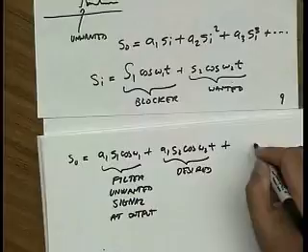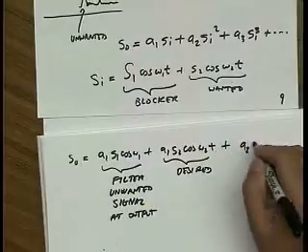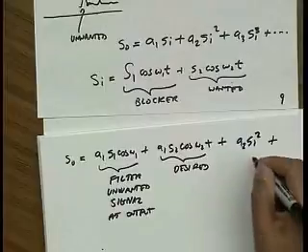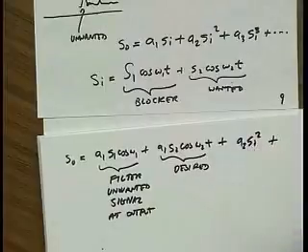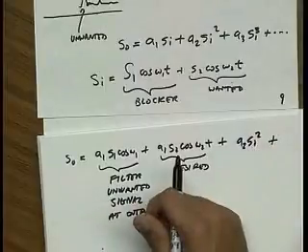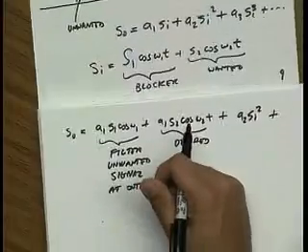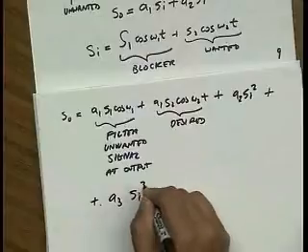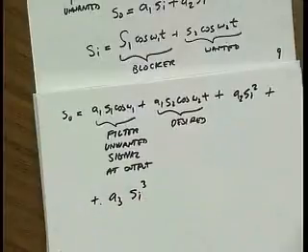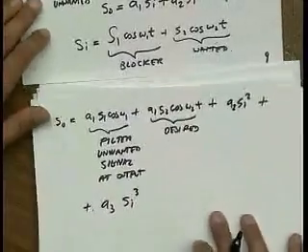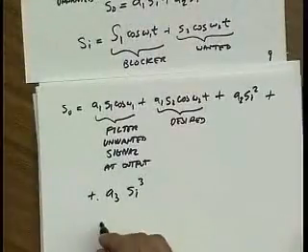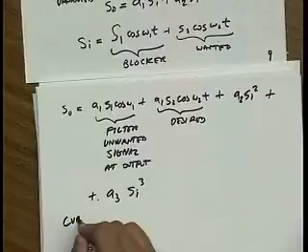And then I'm going to have basically square products. This is going to lead to IM2 tones, right? But again, let's assume I can filter out my IM2 tones. And then finally, I'm going to get this cubic term. And what I'd like to show you is that this cubic term generates all the nasty stuff. So let's expand out this cubic term. So let's focus on the cubic term.